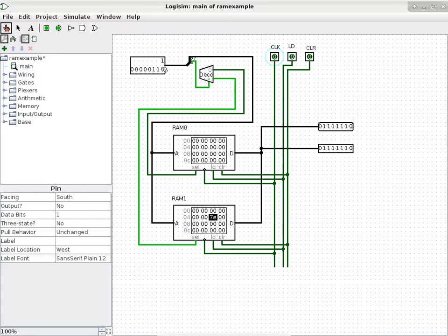So if I just go back to the diagram here, every single step that we did, changing the address bus here, remember, who is driving the address bus? Who is specifying the content on the address bus? CPU. The processor, right? So the processor, at a certain time, it will say, okay, I want to look at location, this is 106 in hexadecimal. The question now is, how much time does it take for the decoder circuit to do its job? And how much time does it take for the RAM chip, the correct RAM chip, to say, oh, you want me to get to location 6.